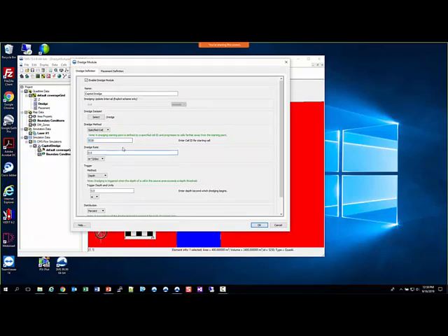We're going to have a dredge rate of 10,000 cubic meters per day. You have several options here depending on what you want to do. So anyway, 10,000 meters cubed per day. Our trigger method we could either do by depth, a certain volume, percent, or time periods. So there's several different options here.